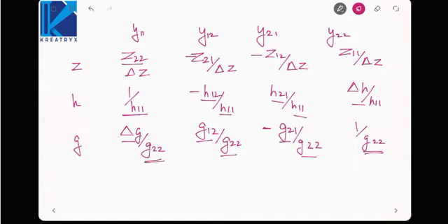Same thing was happening in Z parameters. And the last, transmission parameters. Then transmission parameters for Y11 will be D by B. For Y12 minus delta T by B. Delta T is AD minus BC, determinant of ABCD matrix. Minus 1 by B. Then A by B.